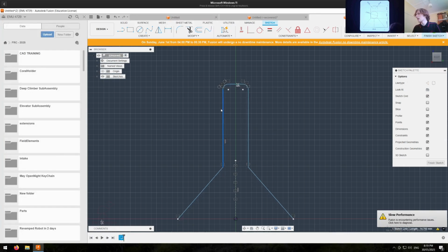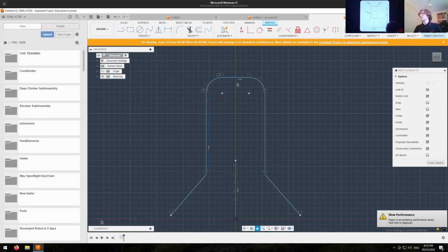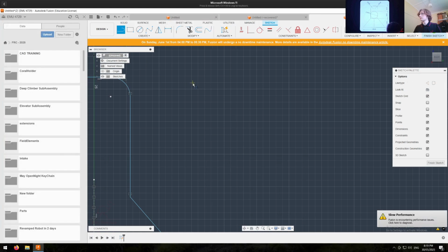Let's see if I drag this out though. Wow. So just to clarify what just occurred there, I'm only going to explain the coincident constraint, and then I'm hoping you can, in your own time, learn the other ones. But if I make two lines, and I select this one, and I select that one, I can then apply a constraint. I can make these 2 points coincident, meaning they're in the same place. And you see how Fusion does the work for me of lining them up.